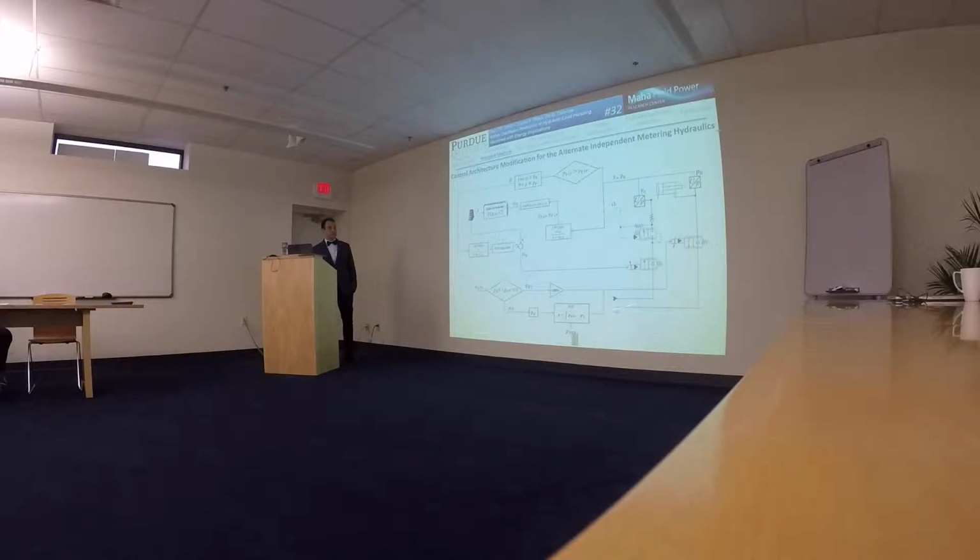So if you can see here now the same controller strategy as before, where this top part is the same as before, where we are controlling the meter in edge in order to control the velocity of the actuator, but we are also controlling the meter out. And here it's a simple logic of this controller. So here with the pressure sensors, we do the balance in the cylinder just to recognize if the load is resistive or overrunning.